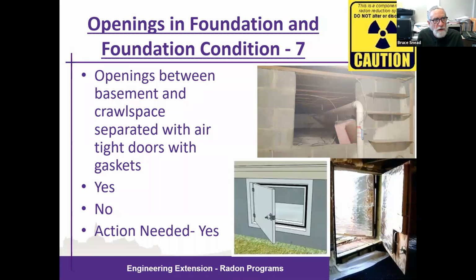Are there openings in the foundation, and what is the condition of the foundation? You're looking at some access to the crawl space here, either graphics or doors that show openings between the basement and the crawl space. That one is wide open. You can see the radon vent pipe there in the center. And the bottom two show weather strip doors that provide airtight gaskets and separation from the crawl space to the adjacent basement area. It's important that these doors, if they are part of a radon mitigation system, be labeled as such. And you'll see that requirement come up again.